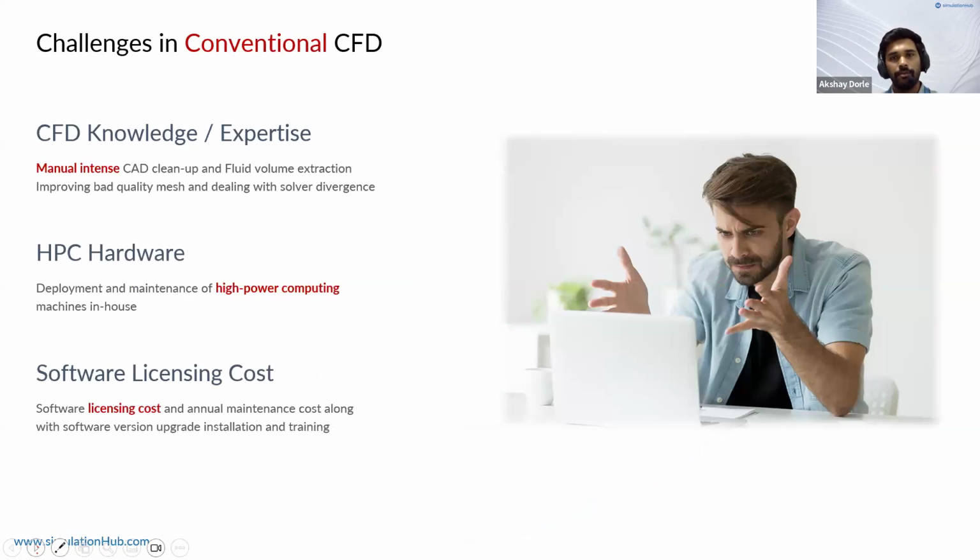The challenges with CFD are that it requires a lot of expertise. We require a CFD engineer or an expert in CFD to accurately model all the steps, choose the right solver settings, and post process the results effectively. Then there comes the hardware cost. Since this is a numerical setup, it uses high performance computing to solve the problems in less time, and HPC hardware might not be available with everyone.